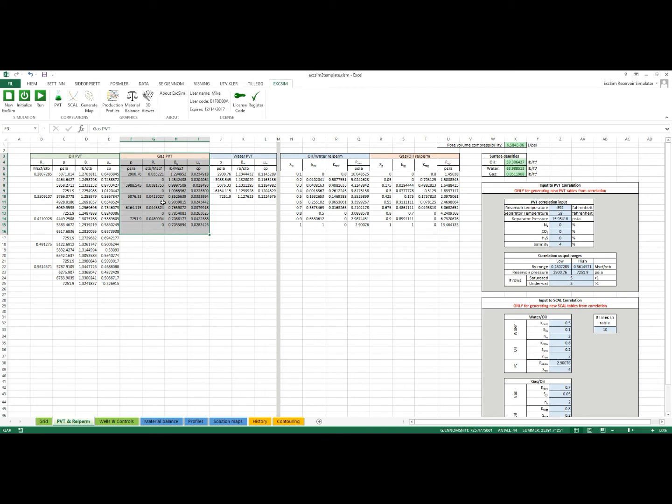The next table, the gas table, is the PVTG keyword from Eclipse. It's the same format, and it's very similar in philosophy to the oil PVT. You got these different sections, and the first line is the saturated, and any other lines are undersaturated. And you have the water PVT data with pressure, water formation volume factor, and water viscosity associated with the pressures.